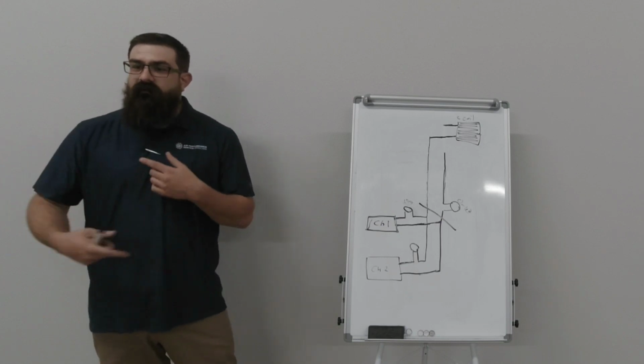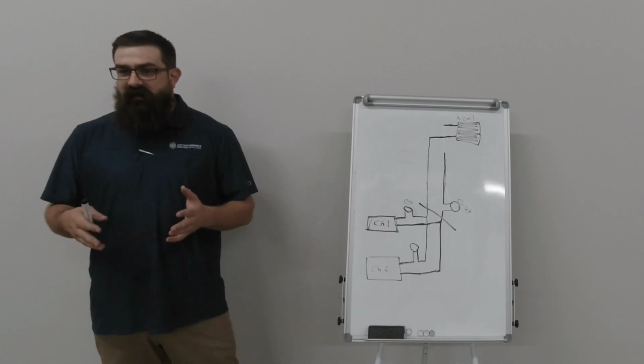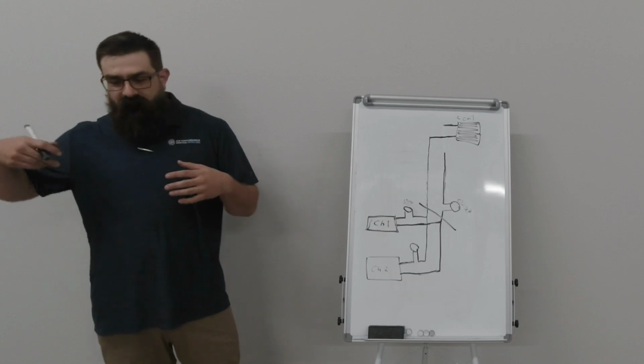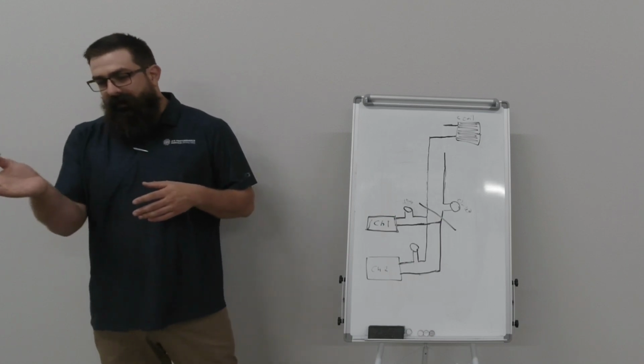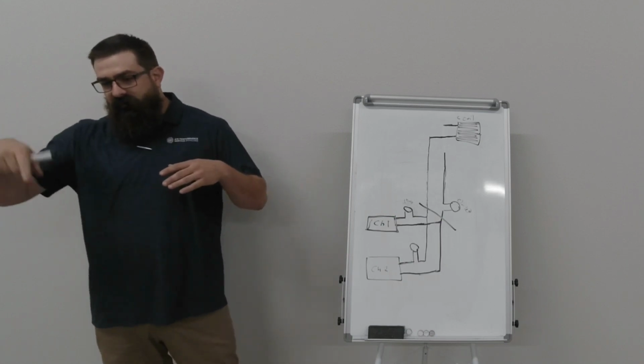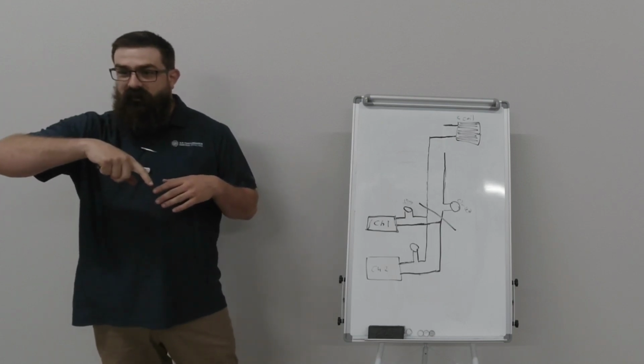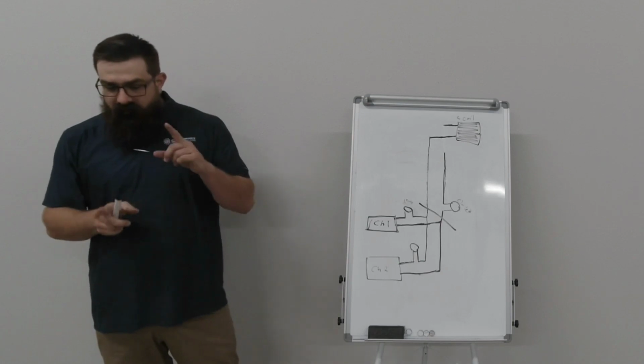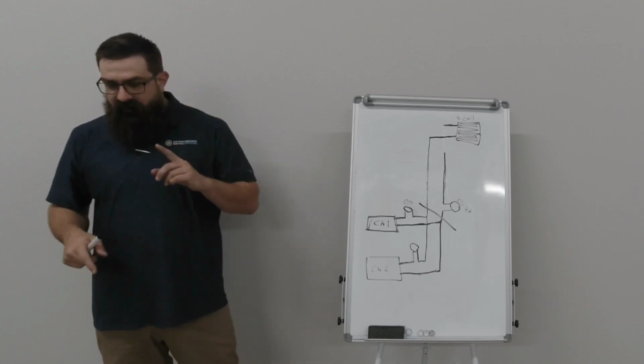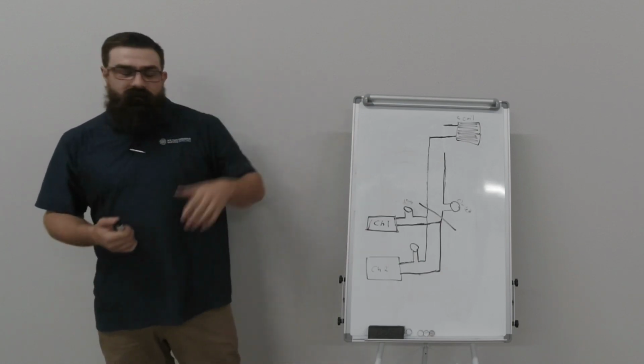That equates to how much flow is going through it, how much temperature is being changed. So if you've got 45-degree water entering, and then you have pressure loss across the coil, and then you also have temperature loss that reduces pressure as well, or increase, you need to maintain a certain amount of pressure in that system to push water through every coil.